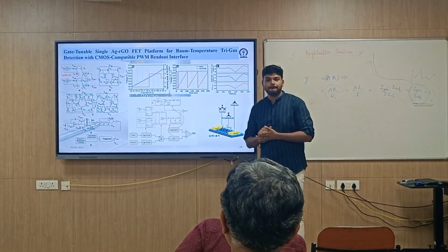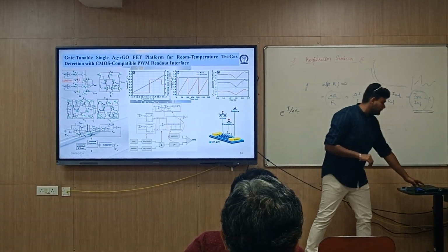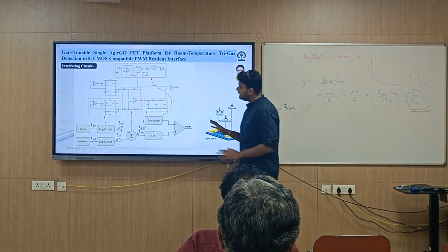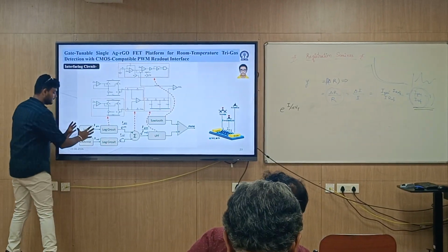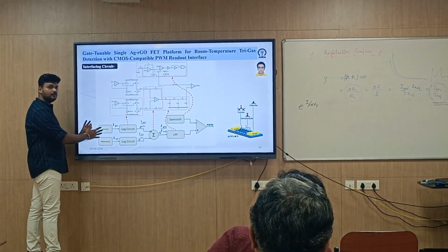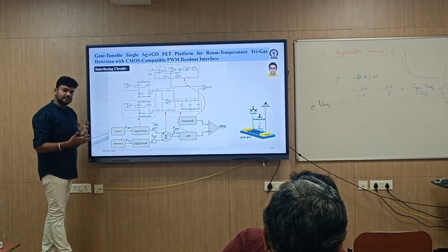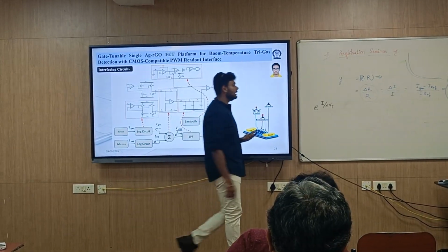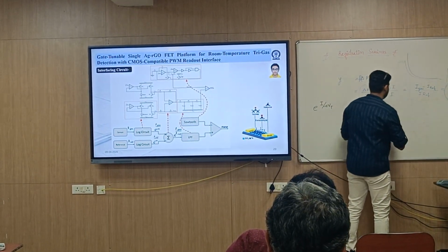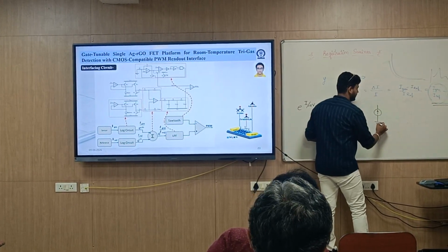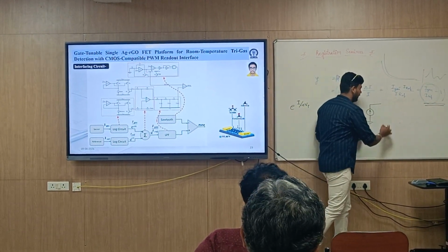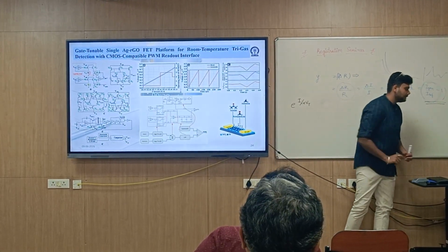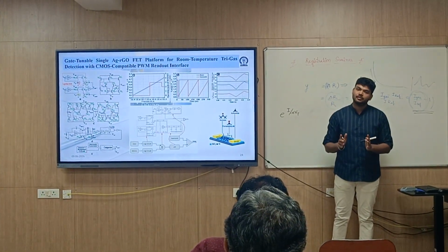And you also need other resistances, right, like the previous one, like a Wheatstone bridge? No, you don't need other resistances here. The best part is reference and sensor; we don't need any other resistance. So the sensor can be modulated like a reference current. And basically, you need two sensors here: one exposed, one not exposed.